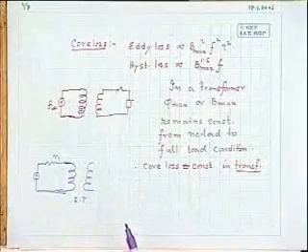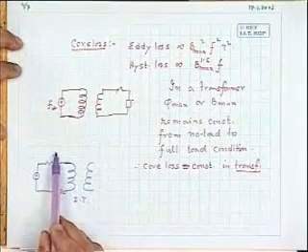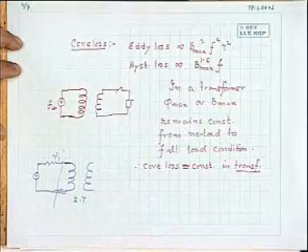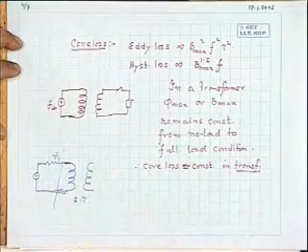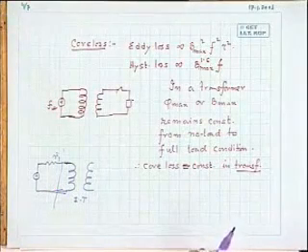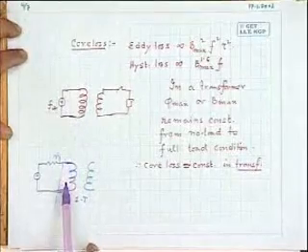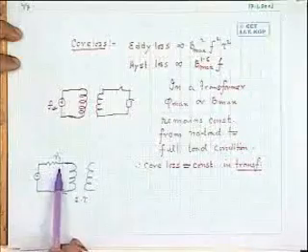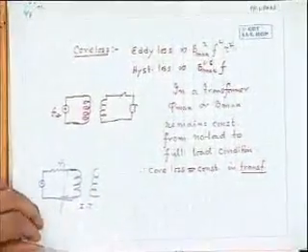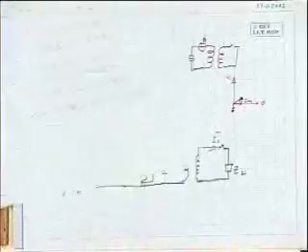Once you show it like this, to understand how to tackle this situation, you may think that this impedance or resistance is in series with the supply. Let us push it to the supply side, and this remains your ideal transformer. It is as if you are supplying a transformer from a source which has some internal resistance or impedance like this. So R1 should be shown in series with this line. Now that is what the resistance part is.